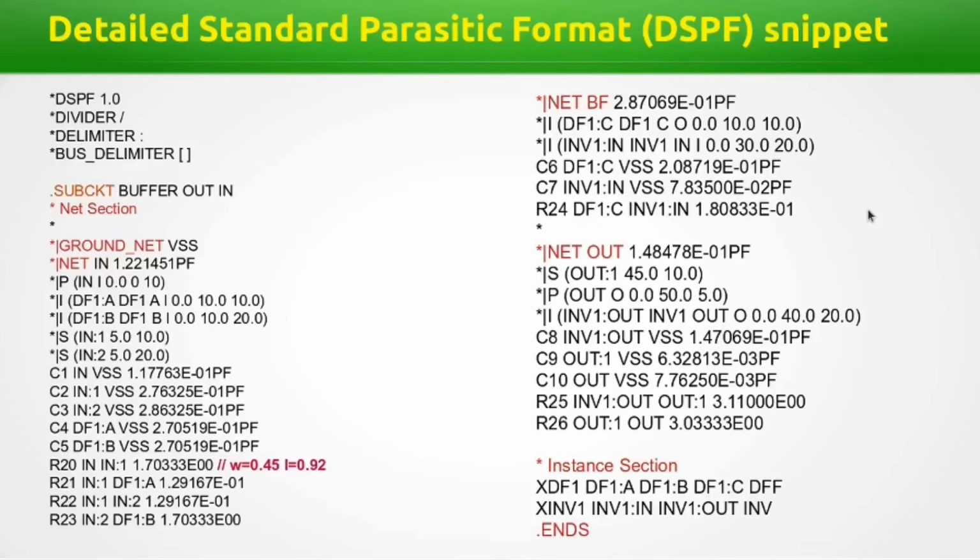This is how DSPF is different, because in SPEF there will be no instance section. In DSPF it will be there. A DSPF is a SPICE ready format, while the SPEF is not a SPICE ready format.